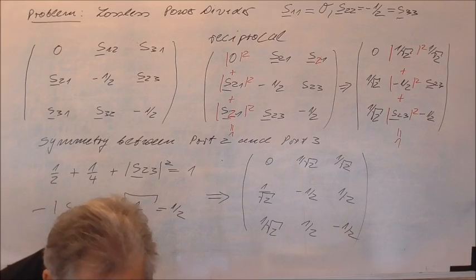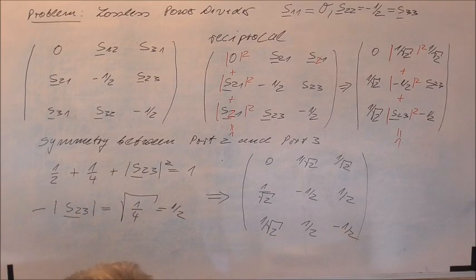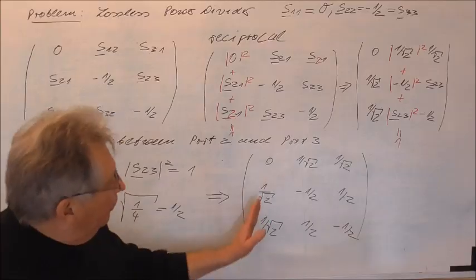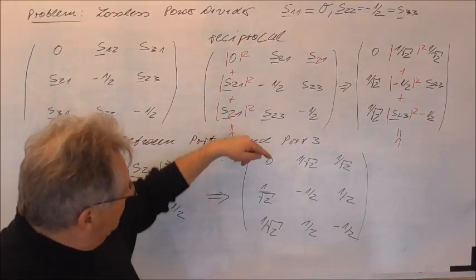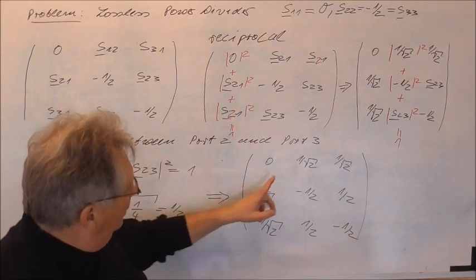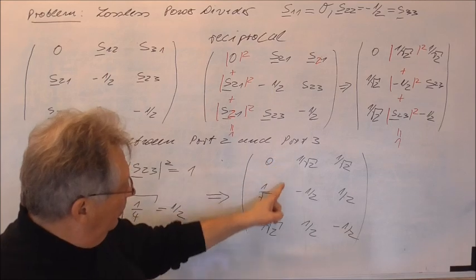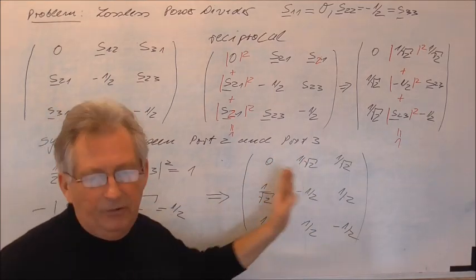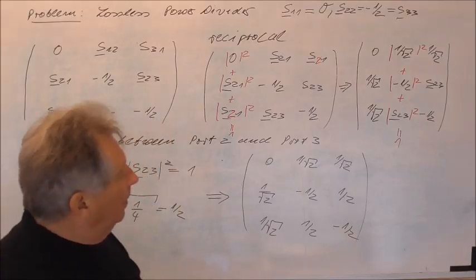Yes, and we don't prove the phase condition here because we consider the transmission line length to be negligible. Now you can prove the phase condition. So you must in principle take this times the complex conjugate of this, and this must be 0, and then you will see that the phase condition is fulfilled.